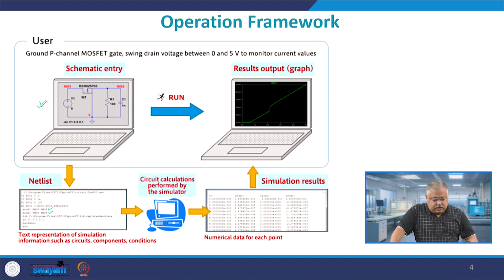If you look at, for example, the first one, we are giving a DC bias of 5 volts here and the component name is referred to as V1. So, I have a V1 here. Similarly, we have a C1 whose value is given by 1 nanofarad and we have this resistor whose value is given by 100 ohms, which you can see here, and so on and so forth.